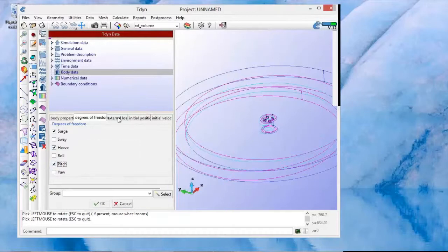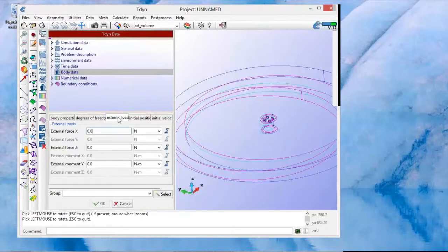Okay, and now, as I was mentioning before, we're going to define external forces in the x-axis, and the point of application would be each of the legs. So it's like we are defining two springs, one in each leg, to avoid the structure going along the x-axis, and we can define it via a function.